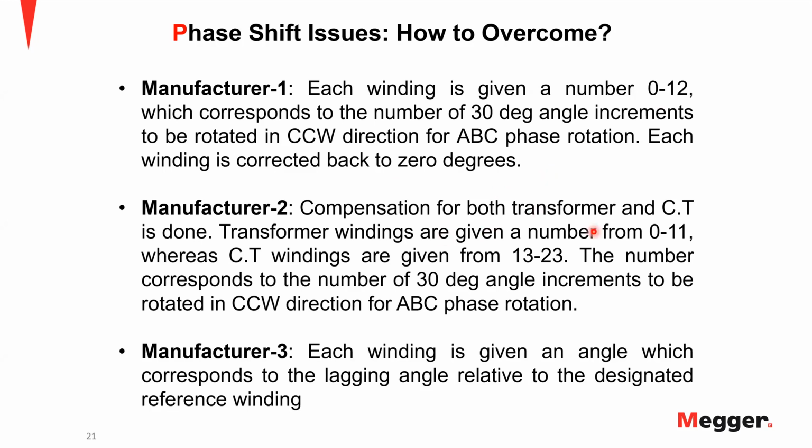And different manufacturers have different styles of working with these compensation techniques. You just have to be wary about what kind of relay you're dealing with. You check the restraint equations, you check the methodology used to decide on the differential logic.